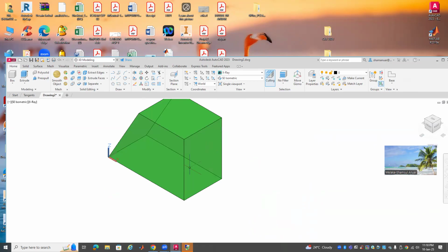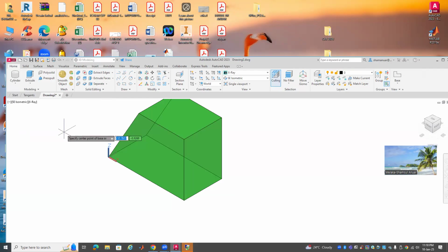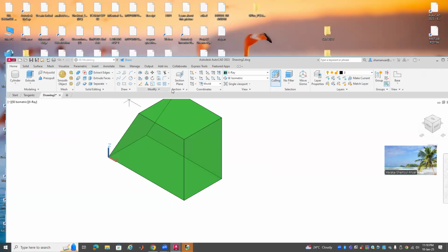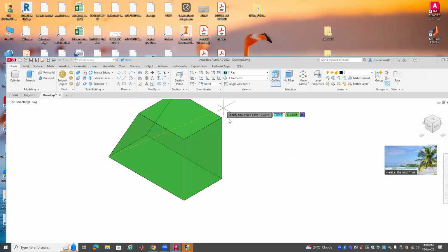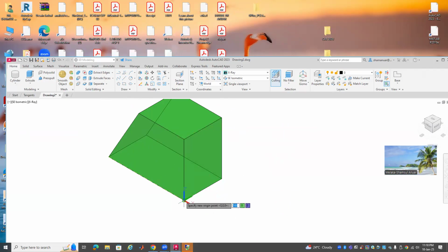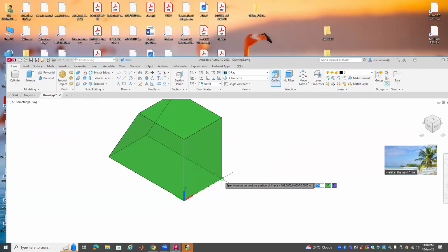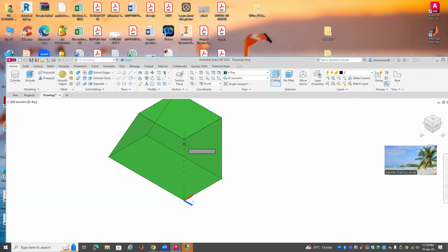Okay, let's create a circle here. Circle there. Cylinder. But before that, you have to move your coordinate system. I'm going to put it here with X pointing this way, while Y is pointing this way. So the Z axis will follow suit accordingly using the right hand rule.